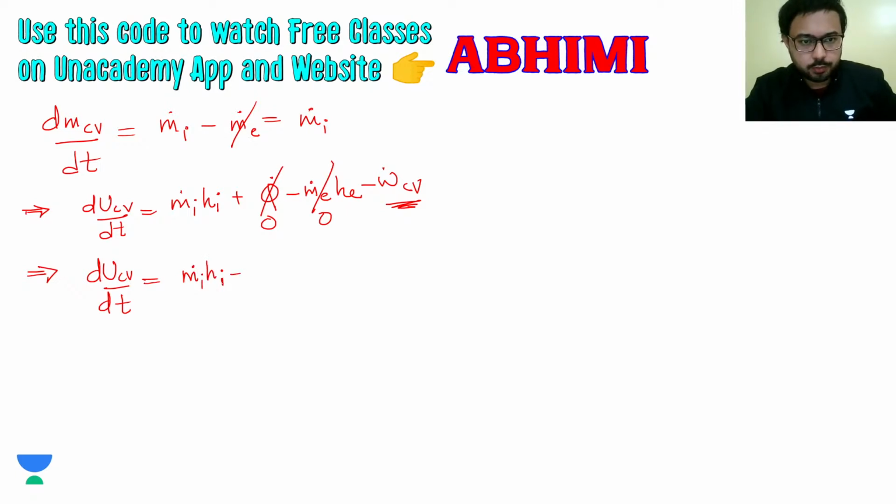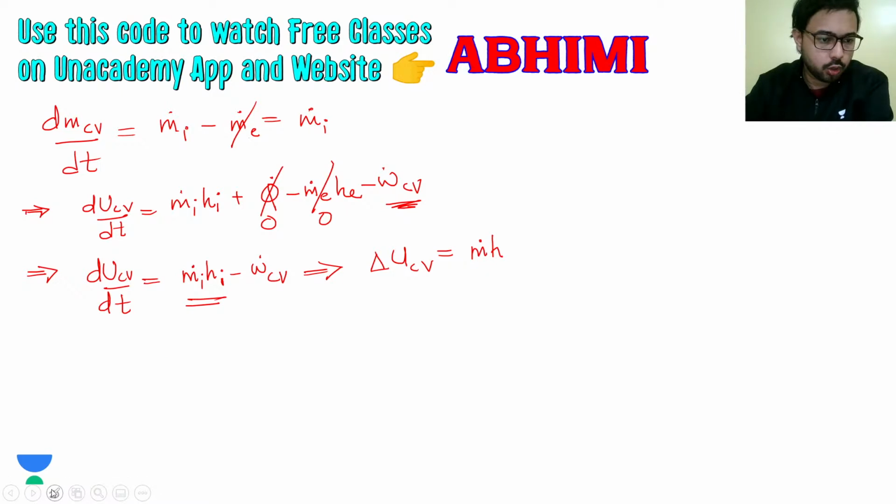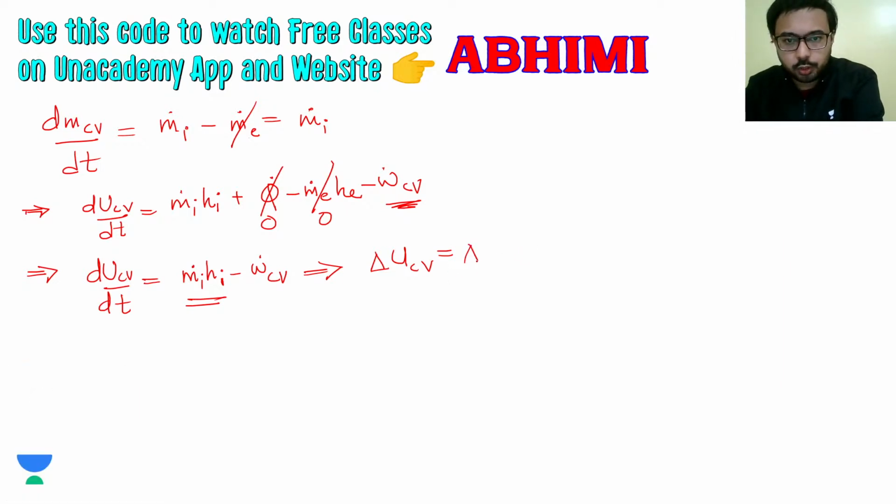I am just writing the one that we have calculated at the top. If we integrate this whole thing, we can write this equation as the change in internal energy of the control volume equal to the change in mass of the control volume times h i, the initial enthalpy, minus the work done in the control volume.